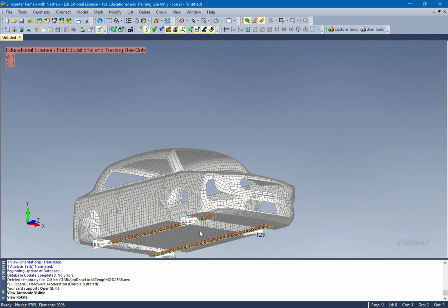I made a SolidWorks model of the body. Then I imported geometry. Then I auto meshed the whole thing. And then you flip it over? Yeah. And then I removed the bottom and put my frame in and then did the bottom. That way, otherwise this wasn't nice like that. And then I extruded these out to get that.